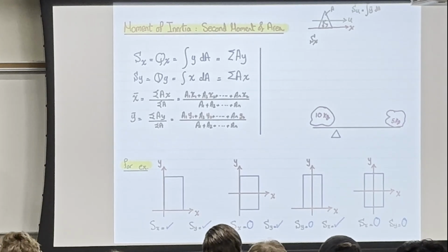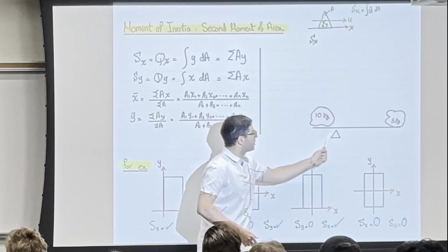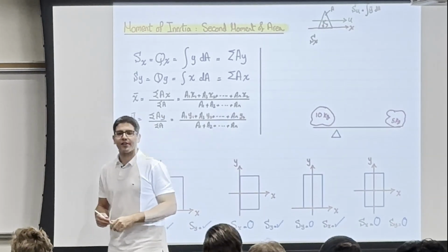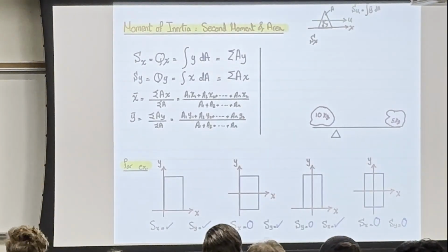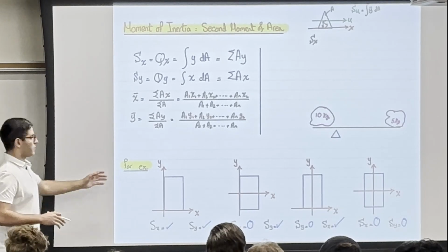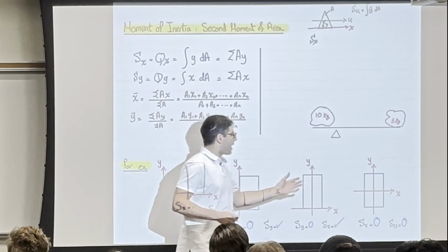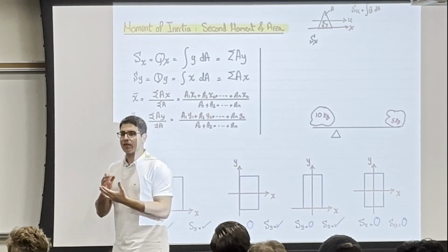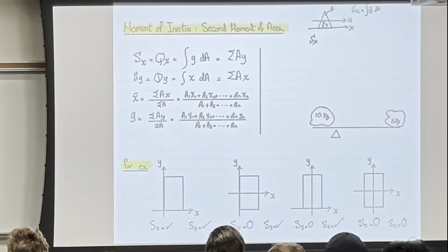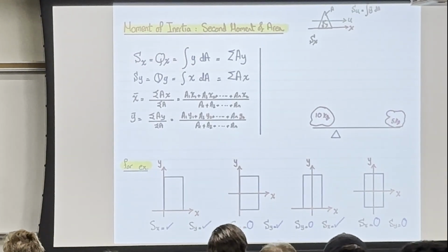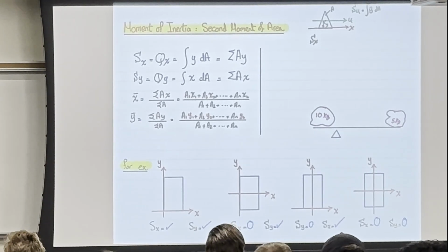So then we went through a derivation process where we found the moment to the left is equal to the moment of the right, and we cancel all the masses. And an important condition here: to derive the centroid and the first moment of area, and later the second moment of area, we need to have a homogeneous cross-section, which means the cross-section should have the same material and same thickness, for example, the same as the span of a beam. That's how these equations are going to be valid, because we found that the density canceled each other, the thickness canceled each other.